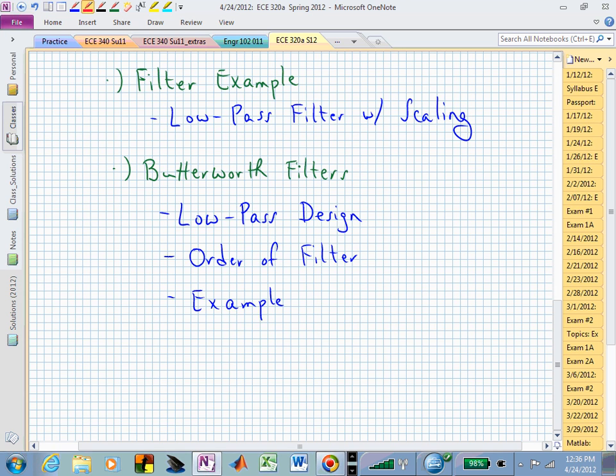The slope in the roll-off range from the pass band to the stop band is going to be much sharper or steeper for the higher order filter. It'll be twice if it was a first order versus a second order. The first order will be rolling off at minus 20 dB per decade. The second order is twice that. It's now minus 40 dB per decade. Meaning we may want a very sharp transition which says, oh, I need a sixth order Butterworth low-pass filter.